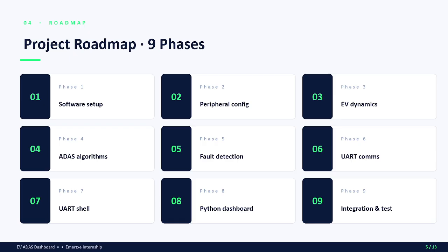The project was developed in nine phases. I first configured the development environment, then set up GPIO, ADC, timers, and UART. Next, I implemented the EV dynamic model, followed by ultrasonic sensor integration, ADAS algorithms, fault handling, UART telemetry, UART shell commands, and finally the Python dashboard.